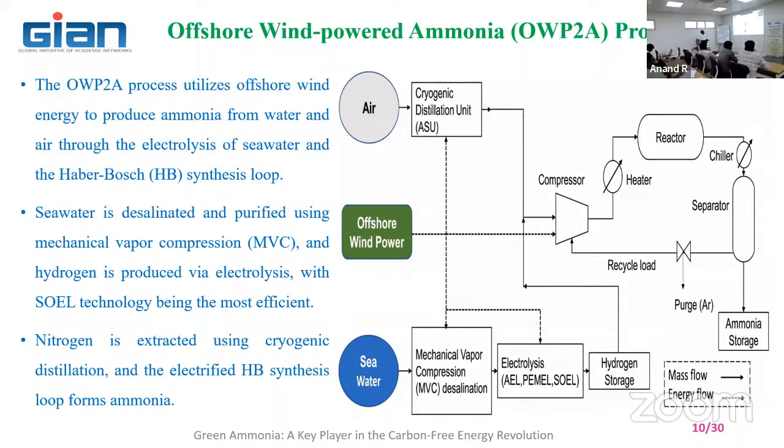By going for chilling, we are not only recovering the waste heat, but also separating out the ammonia from the different mixtures. Yesterday we discussed that. You can operate at the boiling point or condensation temperature of ammonia. Ammonia alone condenses. Other traces will be sent back to the compressor. It is going to be a closed cycle.